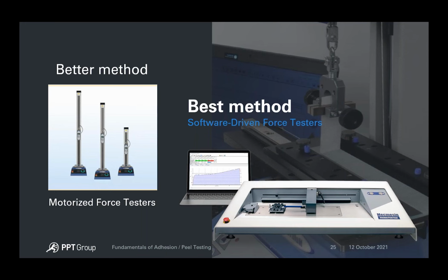So one way of controlling process variation is by using a programmable motorized tester where you can attach a force gauge to the tester. This essentially eliminates the human interaction of trying to guess how far and how fast to test. So with a force gauge in place, it will detect any exerted force, measure it, and display the results, all being done in a smooth, consistent, and non-jerky manner. The how far and the how fast is then programmed into the motorized tester.